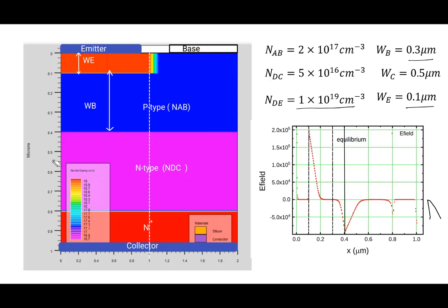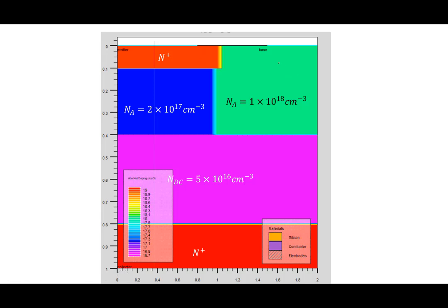Okay. All right. So the base is formed here. Note that what is missing in this particular picture is that, to form a contact, I need a P plus region here also. You will not form a good contact unless you have a P plus region. So maybe more accurate is this particular picture, where under the base I put some 10 to the 18 also, right under the base. But here is 2 times 10 to the 17. Outside the base is what we have used for making the P plus. The actual transistor is running between these points here. So this is a more accurate picture, but all it does is alter the contact resistance and so on. Otherwise it doesn't change too much. All right, so any questions regarding the structure?